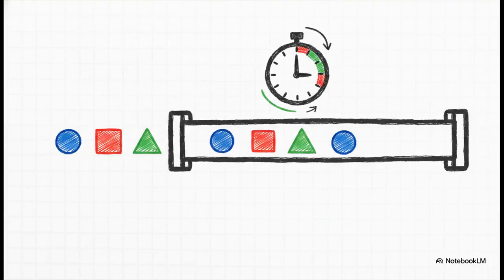Moving right along to Section 2, Multiplexing, or as I like to call it, sharing the highway. So our data is modulated and ready to go. But how do we send it without needing a literally separate wire for every single user on Earth? Well, we share the highway. One primary way we do this is with TDM, or time division multiplexing. Imagine the network is essentially taking turns. It transmits digital signals by assigning these unique microscopic time slots to each data source. You'll see this used all the time in connection-oriented circuit-switched systems like ISDN and PSTN.